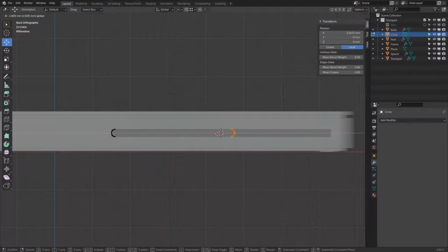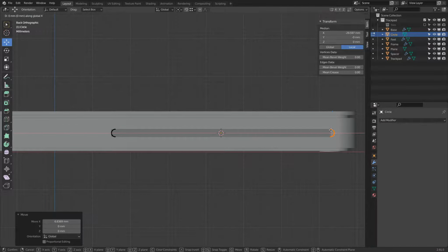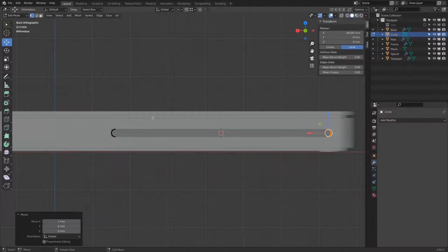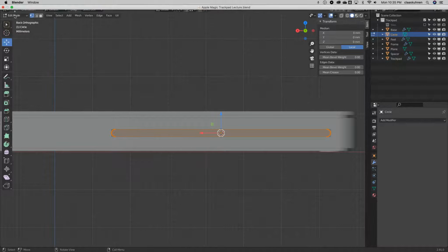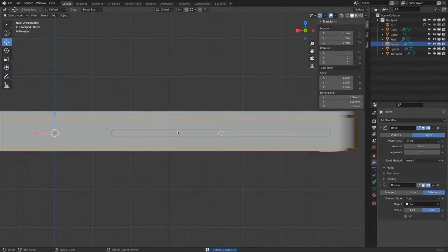So B, bring this over, snap this to there, and then GX1 in this case moves this in. AF. Oh yeah, perfect. We can select these two left and right elements. With A, select everything. With F, we fill it. There we are. Then this element we can remove.